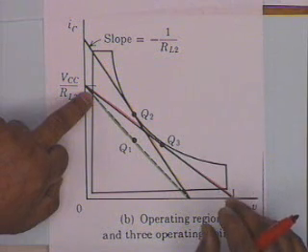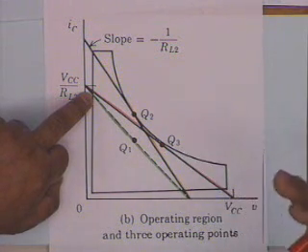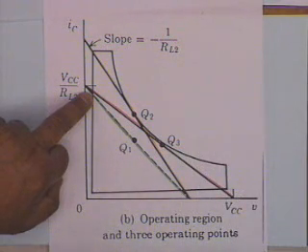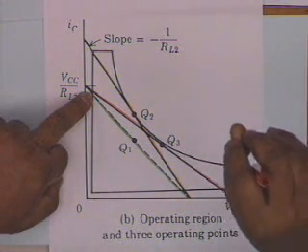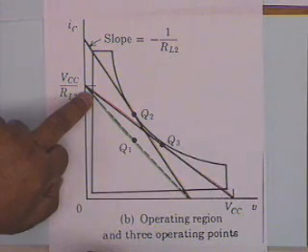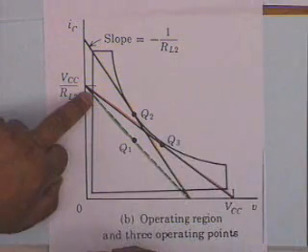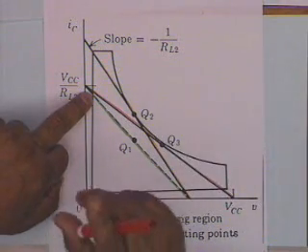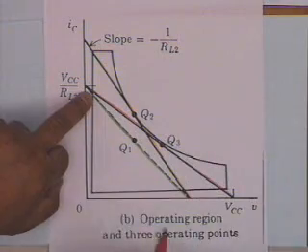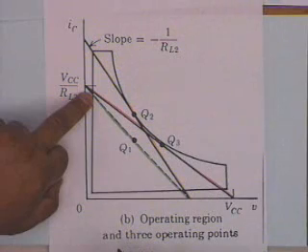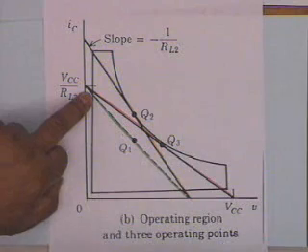In a power amplifier, you require maximum possible swing in voltage as well as current, and you want the transistor to be driven to its limit. You see, the larger the swing, the larger will be the power dissipation in the transistor, but the power dissipation cannot exceed PD, and therefore any Q point on this hyperbola will make sure that the transistor is being driven to its limit.